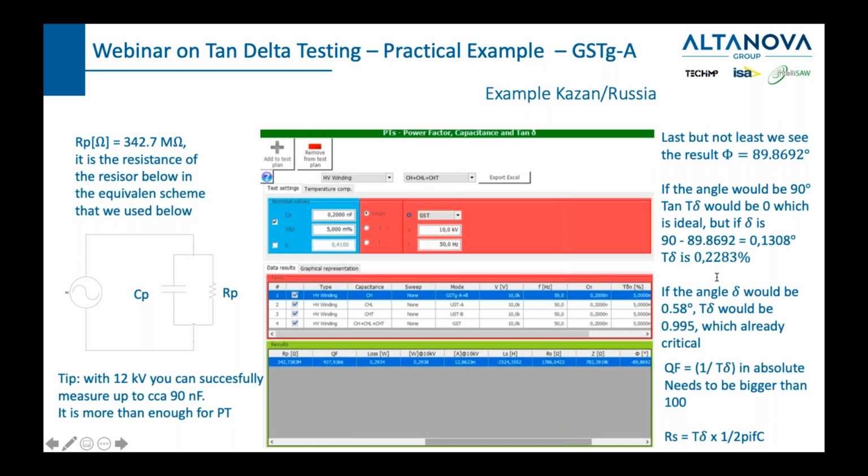And when we talk about 33 to 11, the nominal values, I would always stick to 1% to be sure, maybe even 1.5 in this case. If you are not sure, do the measurement today and then again in a year, or do a voltage sweep today and see if you have a straight line going up or going down, or this line suddenly increases and then decreases. So this would be for Mr. Al-Shamsi.